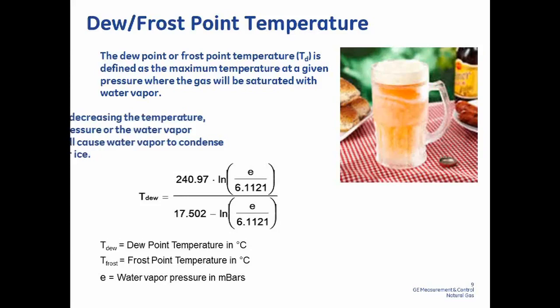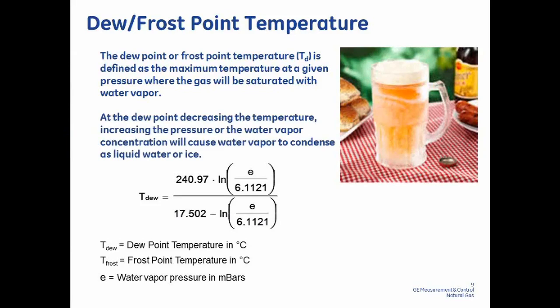This is often one of the things that we run across: people comparing dew point instruments will often see large discrepancies, and if we query the process a little bit more, we might find out that they're not at the same pressure. So then we'll have to make some calculations to adjust for the pressure change.